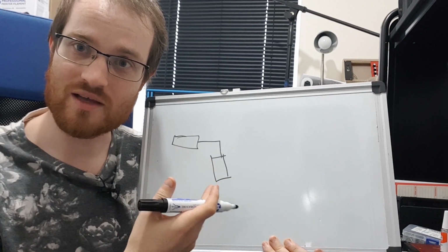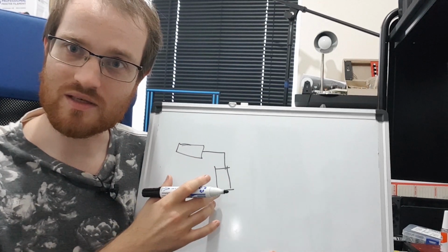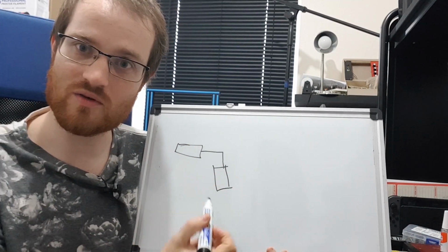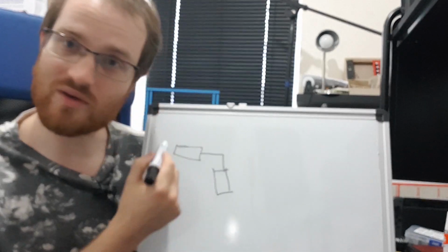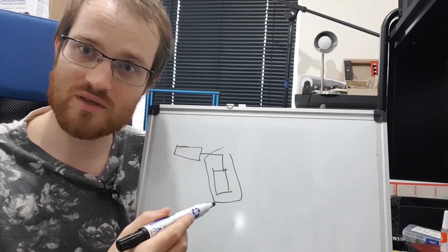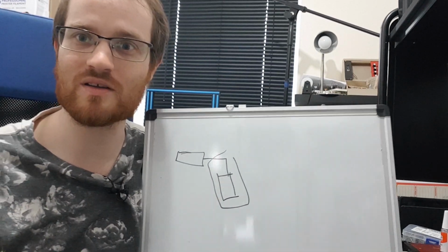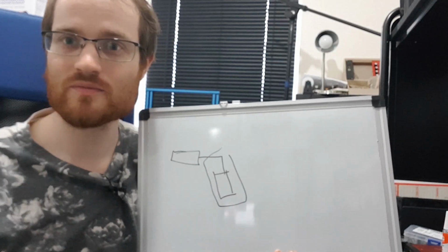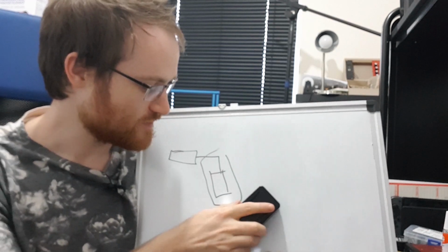we can then model as its own impedance, its input impedance, and the ratio of those two impedances acts as a voltage divider. So you want the input impedance of your filter, which is this part here, to be as high as possible compared to the output impedance of this part here, because then the most ratio of voltage is dropped over this part, because that's how voltage dividers work. If you don't understand that, go back and watch my Circuits 101 video where we go over how voltages and currents and stuff work in series and in parallel.